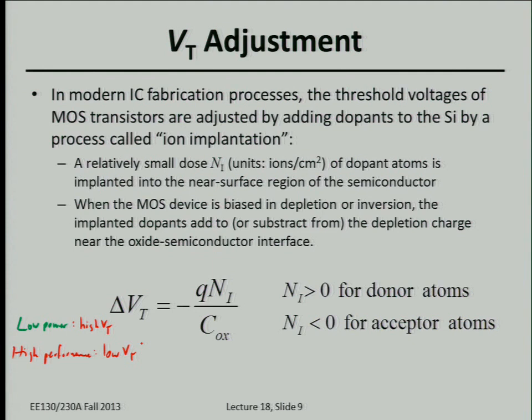Okay. So on the same chip, how do you get transistors or MOS devices with different threshold voltages? Well, we can selectively add some dopants in different regions for different transistors and shift the threshold voltage. So this is what is done. Let's say you have an N-channel device, so that's a P-type substrate. Let's do a simple example here. Here's an NMOS device, P-type silicon. You can form an inversion layer by applying a gate voltage greater than the threshold voltage.